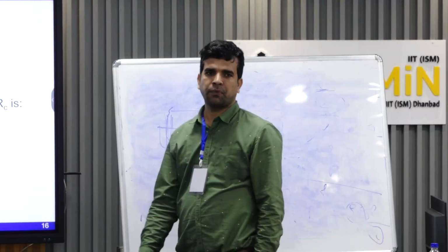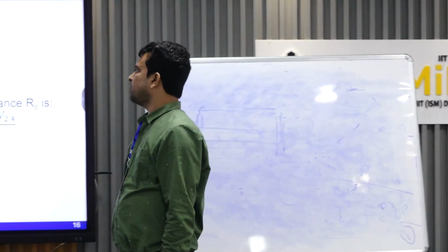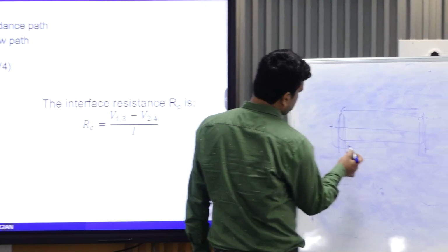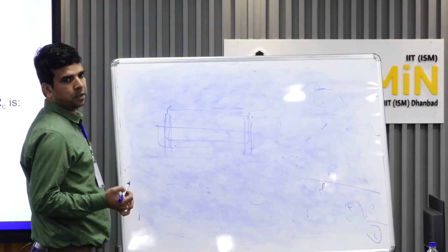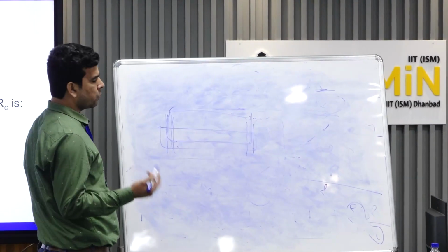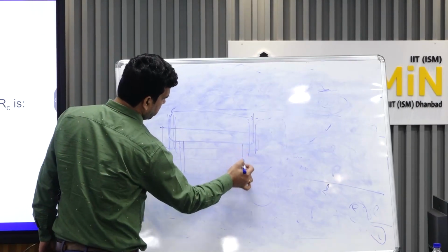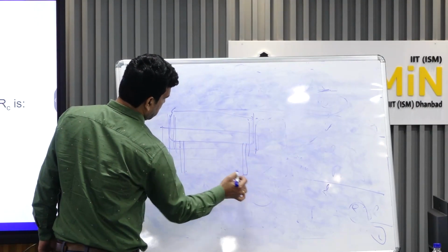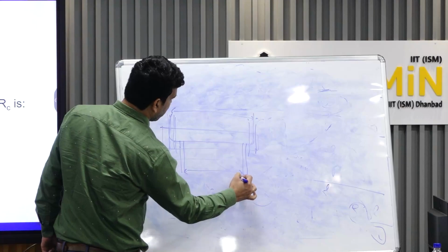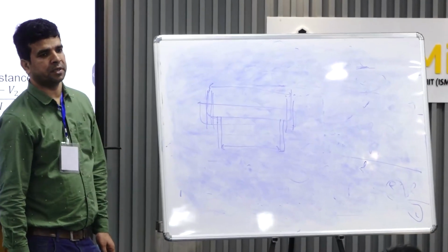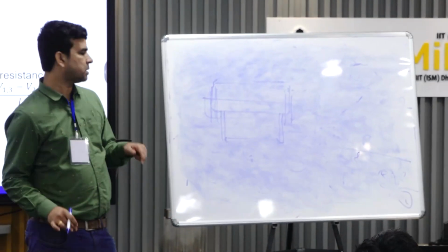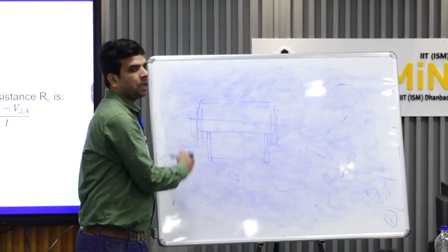Then, just adjacent to the contact, not touching it, we'll create one more pad here and here. On these two pads, I'll measure only voltage in high impedance mode, so no current is allowed through this line.